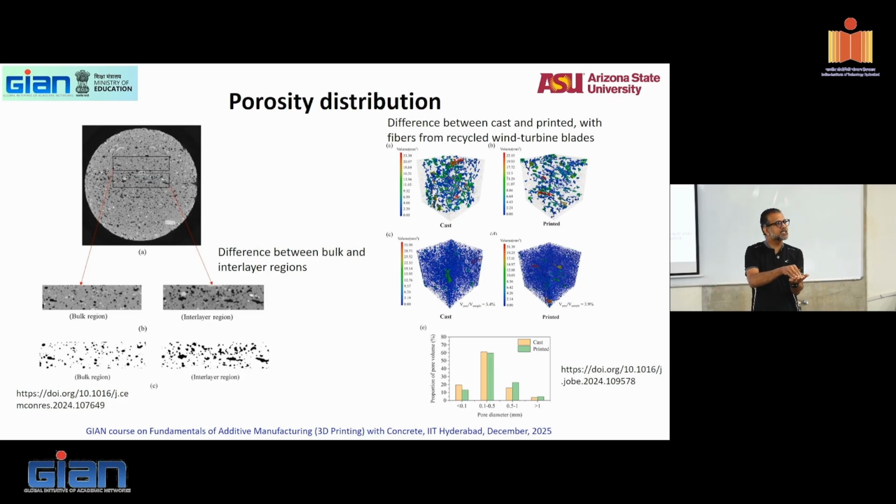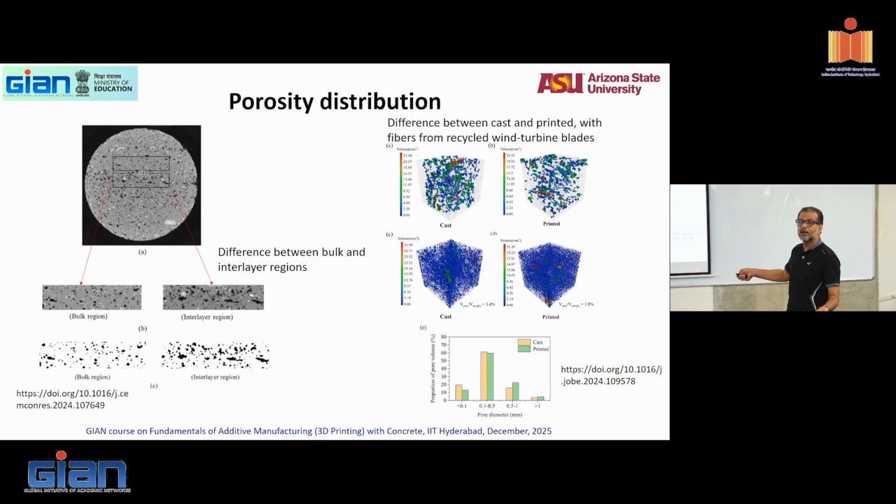And then you can stitch all those images together in another software. ImageJ also does it. You can stitch them all and now have a three-dimensional visualization. I don't have an expensive $500,000 3D tomograph in my lab. No problem. I have good optical microscopes. I am willing to spend some time polishing the samples nicely and making good images. You can create 3D images to see how your structure will look.